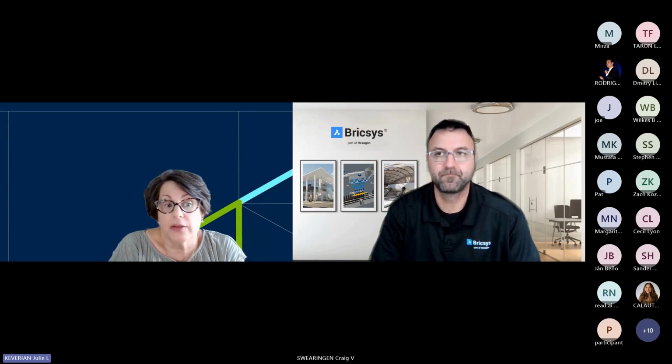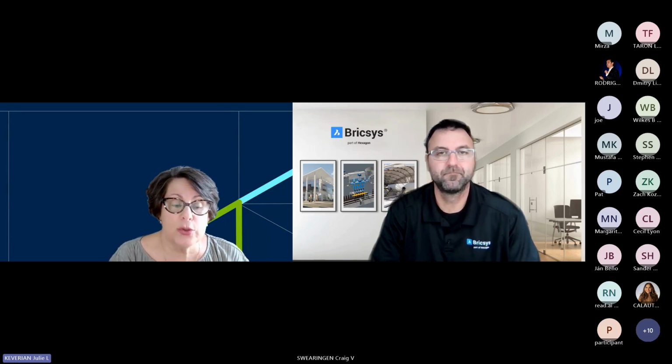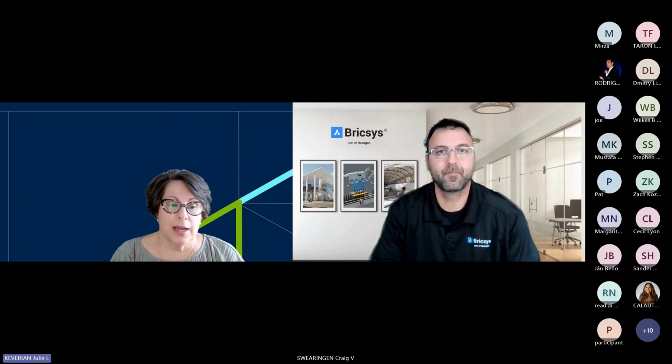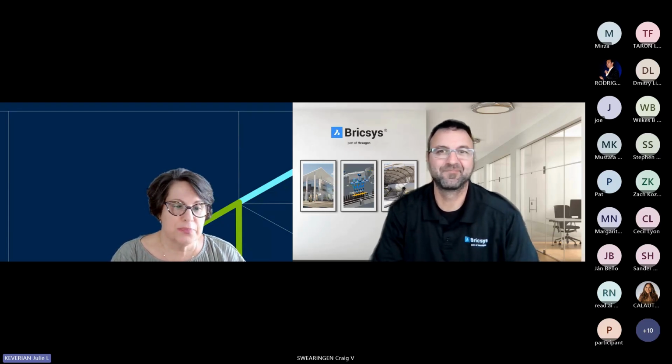If you have a block, for instance, and you know that block always has to go on a certain layer, or you want it a certain color, you can program that into the palette just by right-clicking and going into the properties. So there's, of course, lots of different things to use to create libraries, but we wanted to just point out some of these simple tools that can go a long way to helping get rid of some of that confusion and chaos.